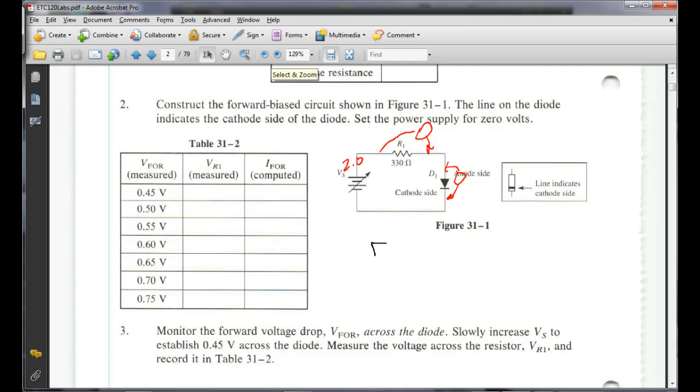Still recording. So we're going to come up here. We're going to change our circuit around. We're going to put our variable DC source. Everybody okay? Reference this to common or ground. I think it's grounded. I haven't taken a meter and decided if that's really a ground. We're going to put our pot right here. Then we'll come over here and put our 330 ohm right here.